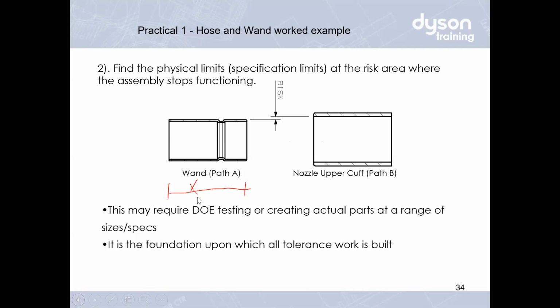No, this length has nothing to do with the force. Am I to control this length? No, you'd be a bit stupid to control this length because it also has nothing to do with the force. So what I'm going to do is control this diameter and the internal diameter, because I know that these two dimensions are the ones that will influence my parameter, my system design requirement of 3 Newton to 5 Newton.